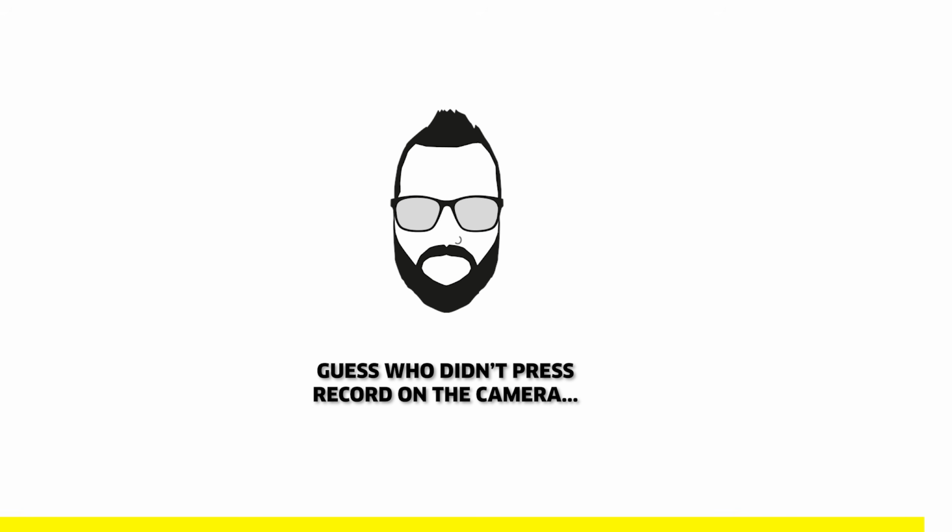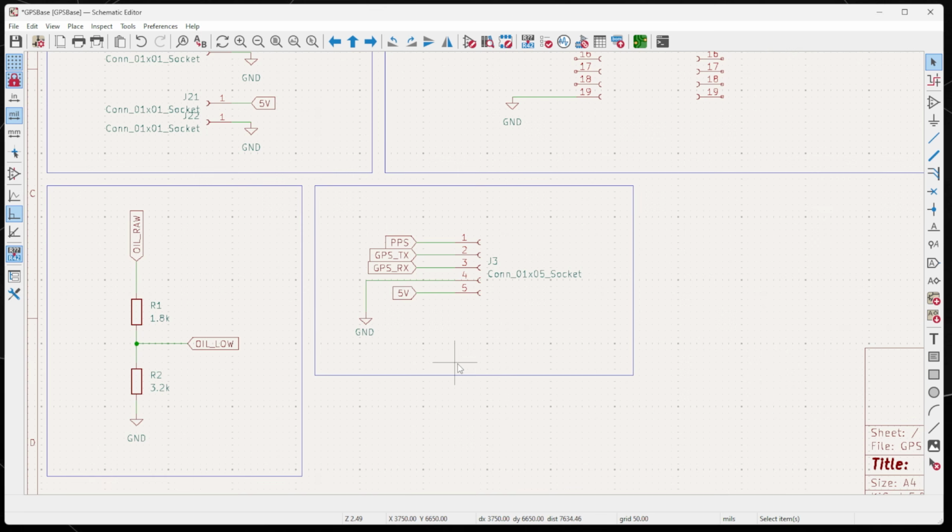Maths. We know we need an ESP32 with an ADC input that we can sense that voltage from. And we know we have a 14.5-ish, like a dirty car battery signal that we can use to power the thing. So we need to make a PCB. I've actually already done it. So let's just take a look at it and I'll explain what I've done.